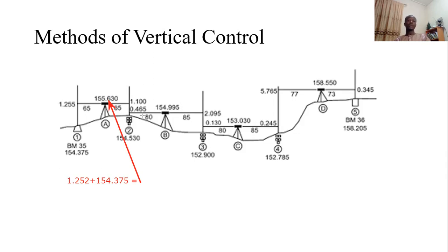All right, so we now get to know the height of the instrument. Then we need to now find the height at this point. So what is the point? It's the reading that we get minus the height of the instrument. That will give us the reduced height here. Then we keep on and on. So subtraction, addition, in fact, what we call the rise and the fall. We also have the height of collimation.